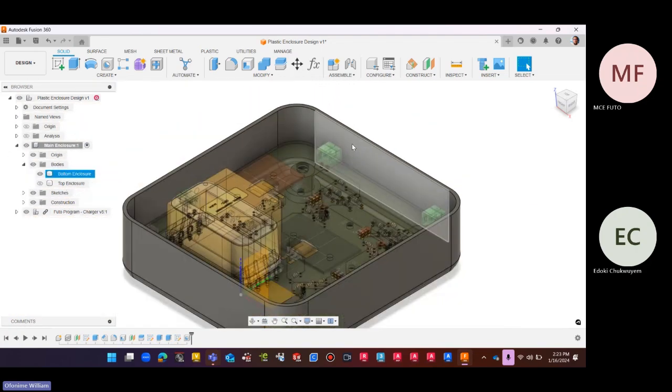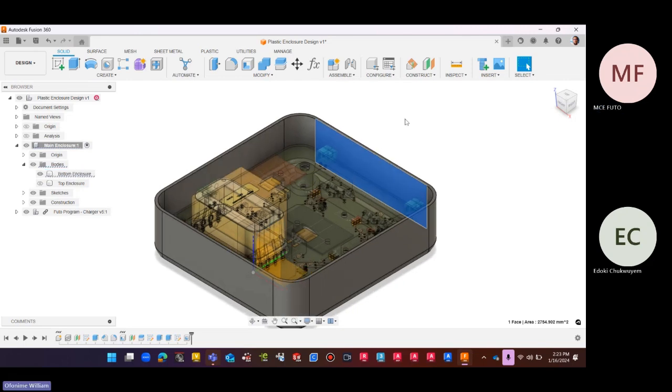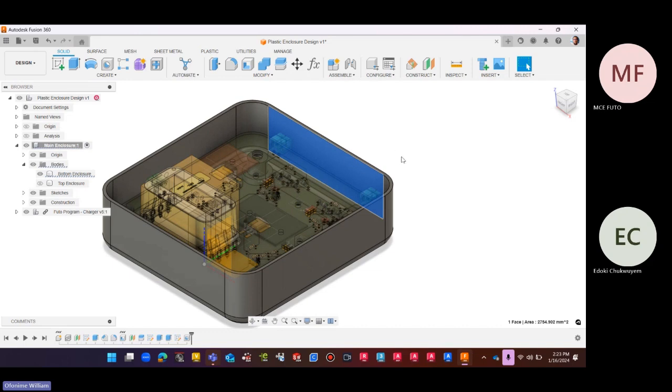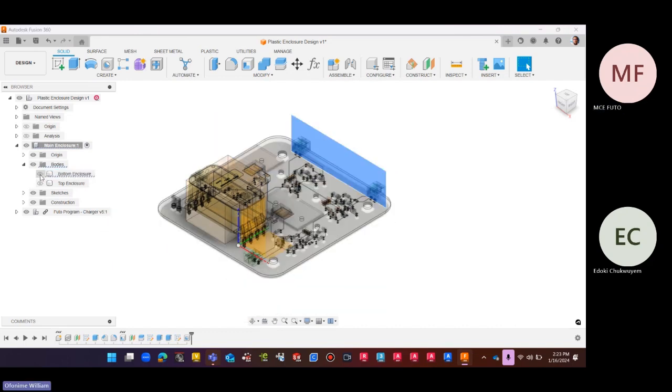So I'll just come over to this point. Like I said, it's the beauty of Fusion. You click on the model geometry and use it as your sketch plane itself. Understand? It has consequences, but with the subject matter we are looking at, those consequences are not very grave. It's something you could always find your way around. So that's why I'm showing you how to get it done using that method.